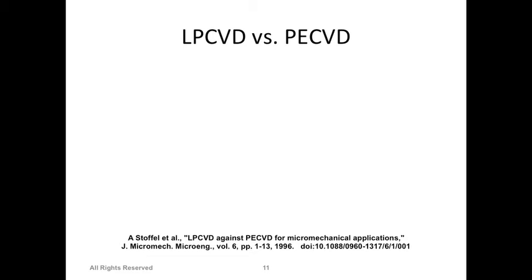In case of PECVD, we can have much higher deposition rates, about 100 nanometer per minute, about 50 times more than what you can achieve with LPCVD, because the gases are more reactive in a plasma enhanced environment. But the film quality is not that great. Okay, the third difference is the temperature requirement, which is one major difference. Which requires a high temperature? LPCVD, and the temperature range is about 600 to 800 degrees centigrade. In PECVD, it's about 250 to 400 degrees centigrade based on different gases.